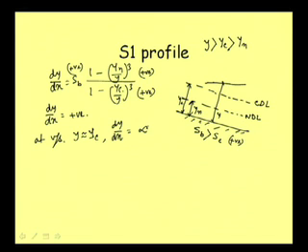And when dy/dx is becoming infinity, what does it mean? This implies the profile meets the CDL normally. So here the profile will be meeting the critical depth line normally, and it will be going like this.